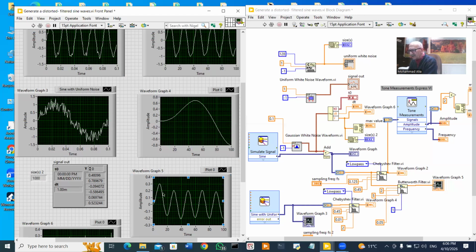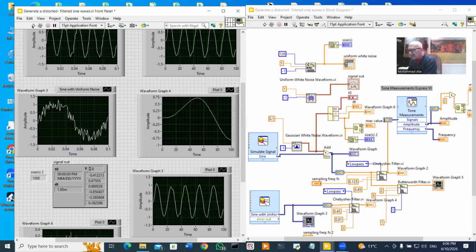This low frequency side could be managed also. Instead of 0.05, maybe if I put it 1, let us try. It is better. Okay, so there is no end for that. You can change it in the direction you want by variations of the frequency and the frequency limits and the ripple values. And the ripple values are generally for Chebyshev filters. The Butterworth filter does not require that because it is leveled. It is leveled, as you see here. It has a good level.